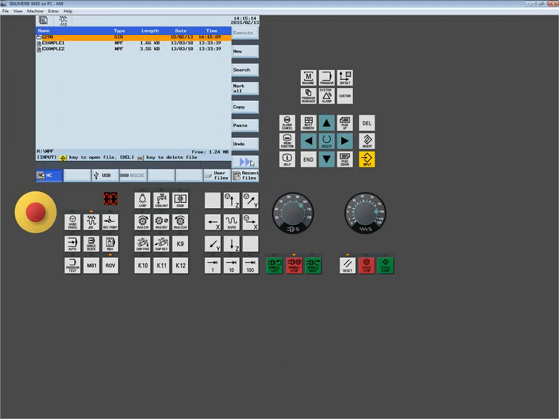From there, I can start to create other folders. Certainly I don't need to use folders. I can have part programs residing right in this directory. As you see here, I have an example one, this MPF file, main program file. But what I am going to do is go into my G290 directory, and this would be the destination where I want to copy that program to.